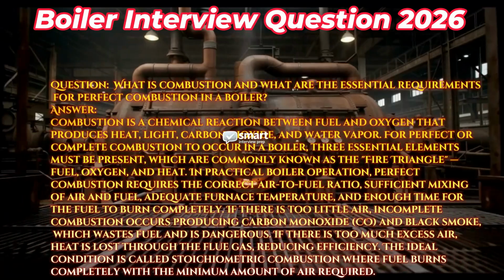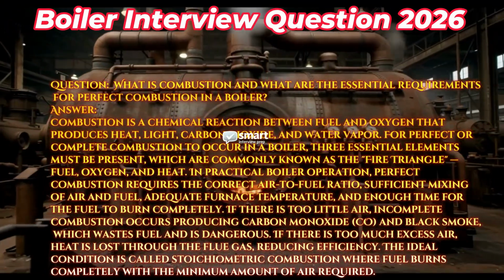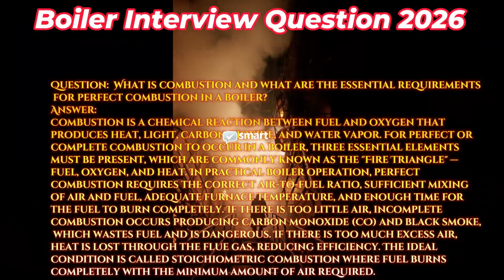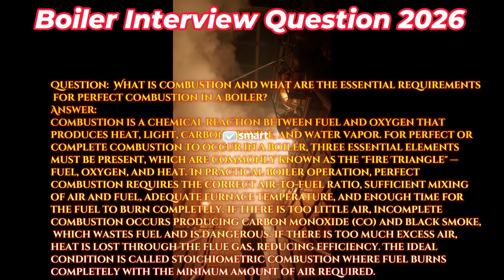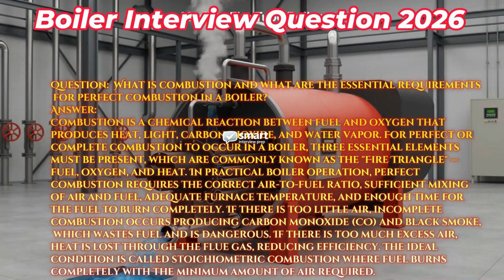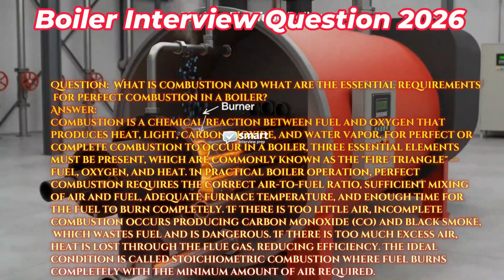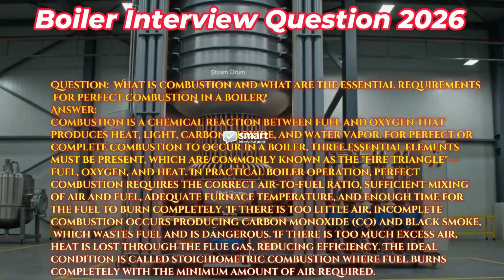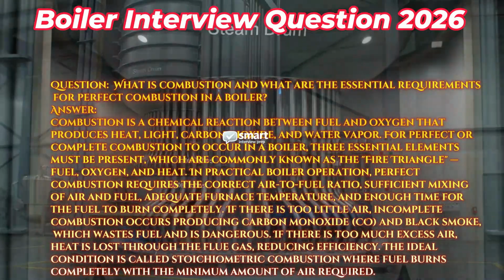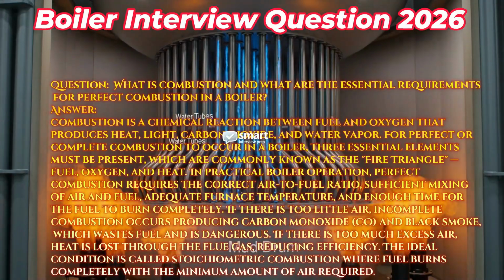If there is too little air, incomplete combustion occurs, producing carbon monoxide, CO, and black smoke, which wastes fuel and is dangerous. If there is too much excess air, heat is lost through the flue gas, reducing efficiency. The ideal condition is called stoichiometric combustion, where fuel burns completely with the minimum amount of air required.